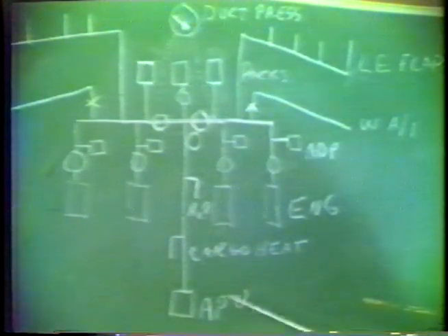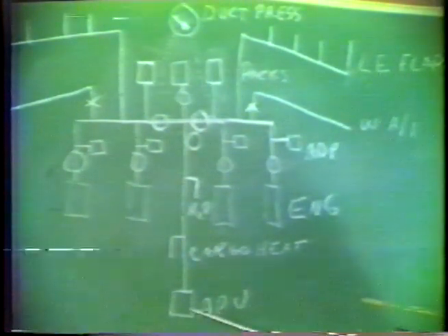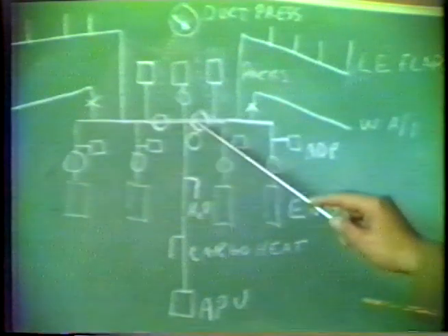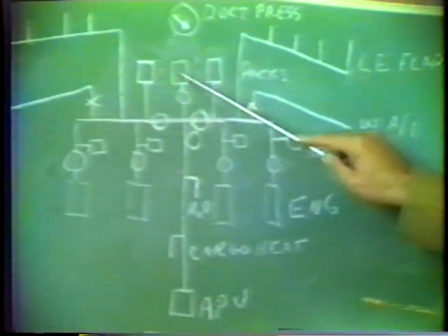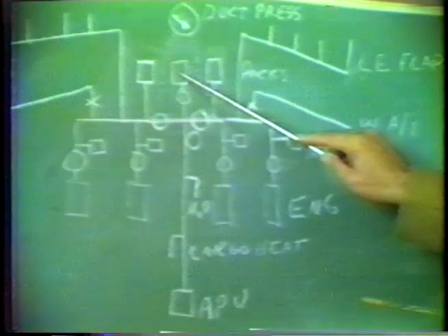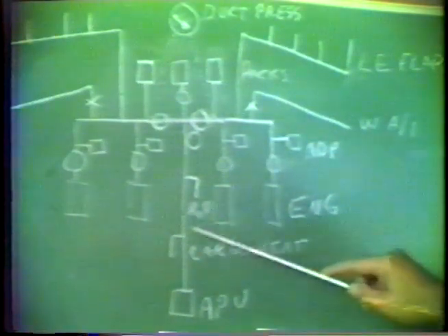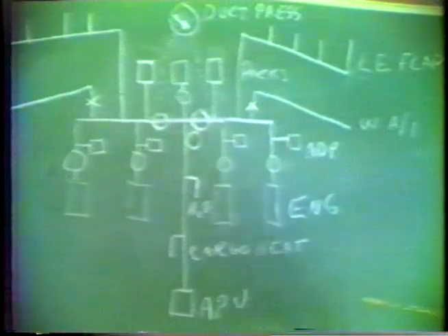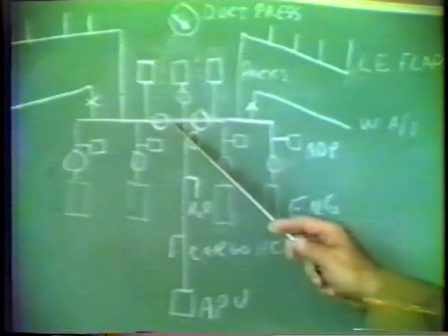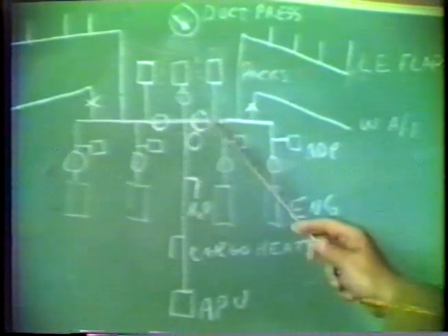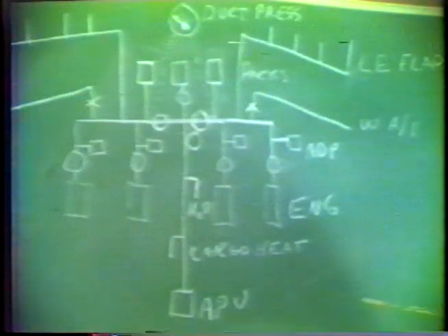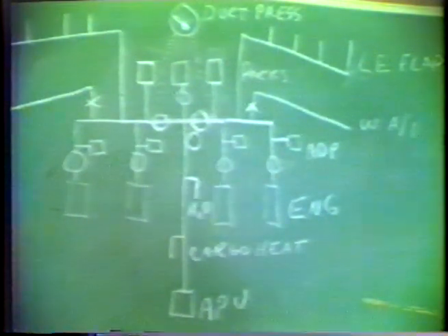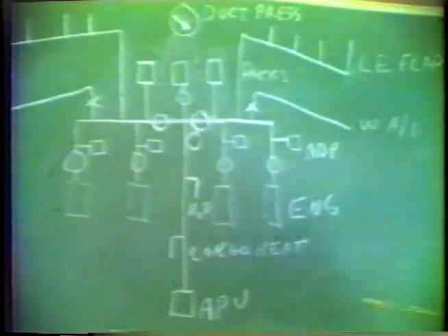If ground power or APU is used, then with the isolation valves closed, only pack number 2 can be operated, and the cargo heat and water. Of course, these two you won't care about on the ground. On operation, normally the isolation valves are open, and they are only closed with a pneumatic leak or a problem where you want to boost pneumatic pressure up.